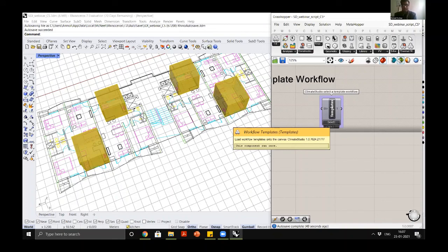It will take time. But just to give you an idea, for IMAC, you will have different spreadsheets for different cities where the upper and the lower band of the comfort ranges is given for different types like natural ventilation, mixed mode, or air conditioned. You can use those spreadsheets and bring your operative temperature data into them, and then it's Excel. I'm not here to explain Excel. So you can use Excel to compare both of these values. You will get your answer.